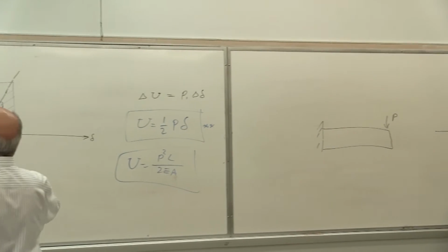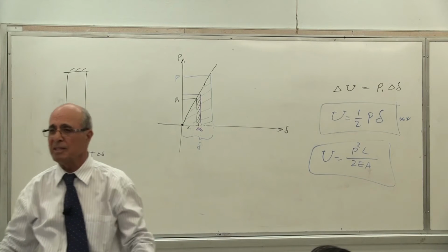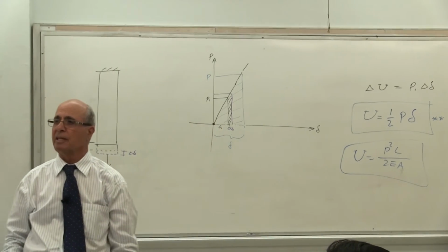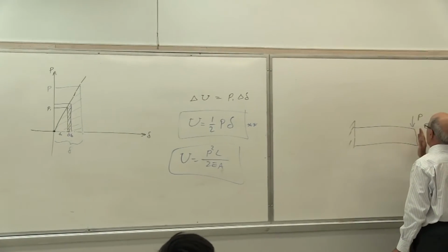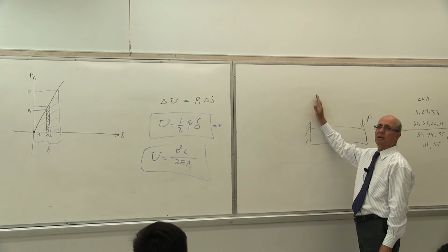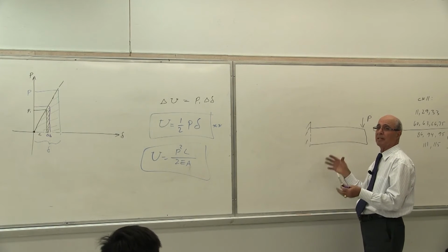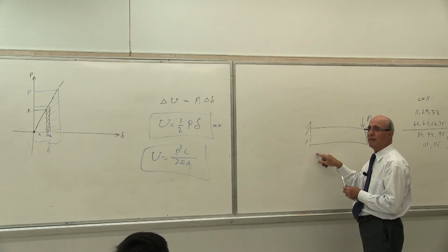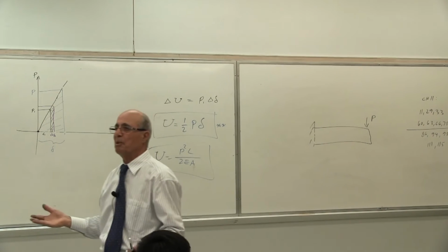Here, if I color code it, let's say all of this becomes dark red. Is that because all of them are participating the same amount, except, of course, stress concentration, which we are neglecting? Everybody understand that? As you have done all your homework, you know that stresses change not just this way, they change that way as well. So where will I get the maximum redness, if red is the highest energy? At the end, on the top and on the bottom, because on the neutral axis the stress is 0 and the strain is 0. Everybody understand what I'm saying?